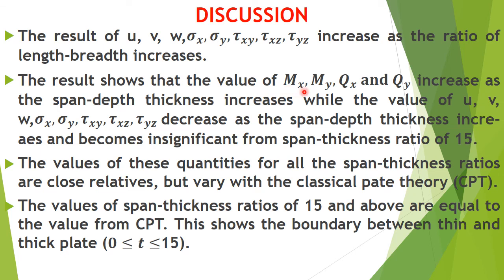But the results show that the value of moment and the shear forces increases as the span to thickness ratio increases, while the value of these quantities, the displacement and the stresses, decreases as the span to thickness increases. And this becomes insignificant from the span ratio of 15.